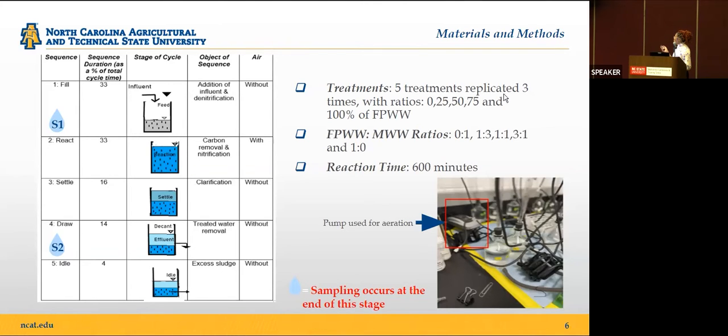This pump here is what we use for aeration. And like I mentioned, sampling occurs at the end of the filling step and the drawing stage. So at 98 minutes into our experiment, as well as 574 minutes into our experiment, we sample the water each time.